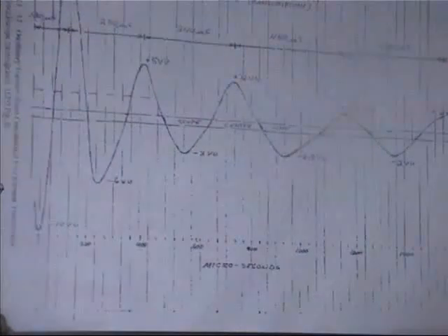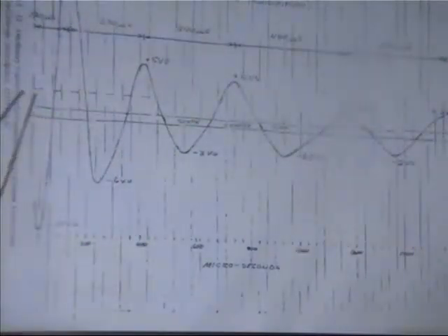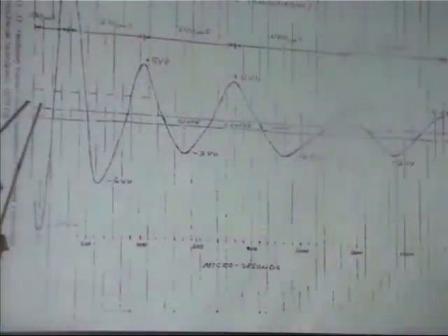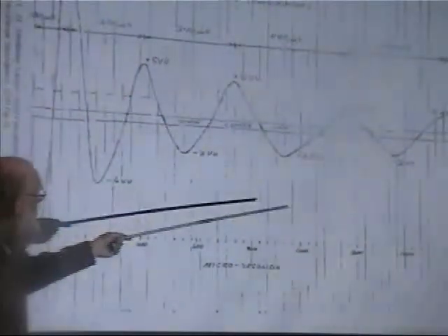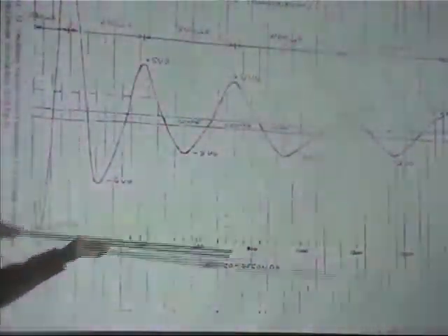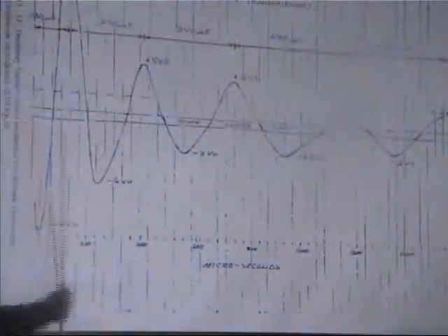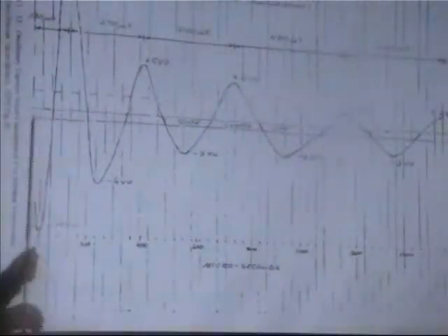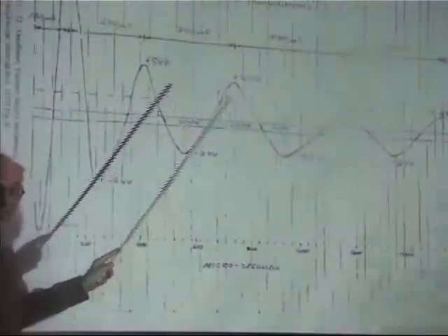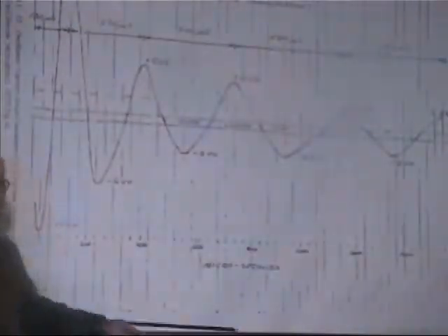Keep going. Okay, now this is the oscillatory discharge of these waves in a Tesla coil configuration, which is basically the frequency becomes slower as the energy exchange continues. Unlike the simple coil capacitor where we're locked into a certain frequency, now what happens is we have a chirp instead of a whistle. The frequency goes down as the energy goes down.